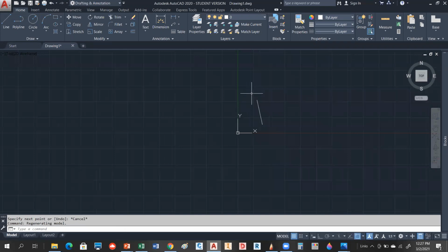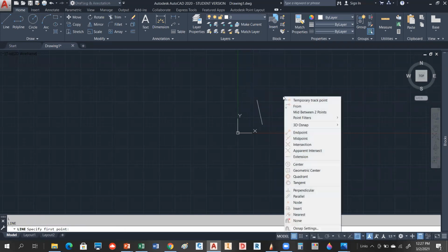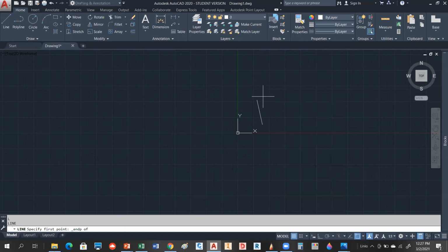Then I'm going to have another line, attached to that. I'm just going to guess. Let's say that bearing was 49 degrees northeast. So then I would say at whatever my distance is, 200 feet, at north 49 degrees east.